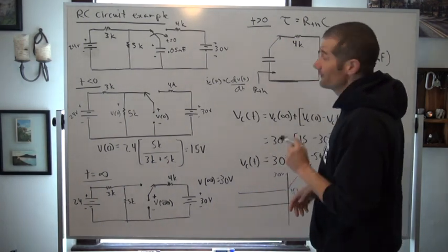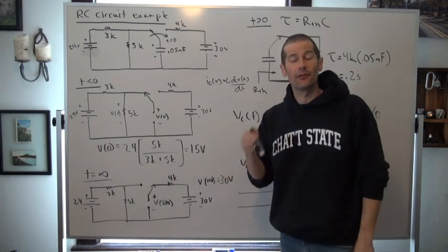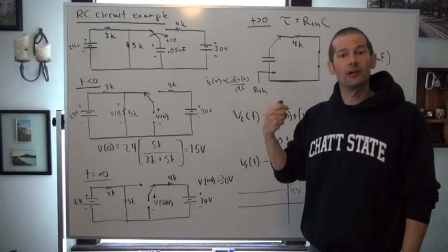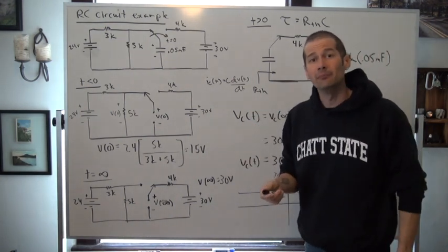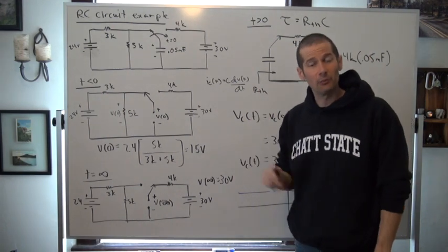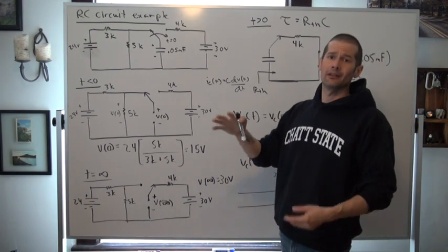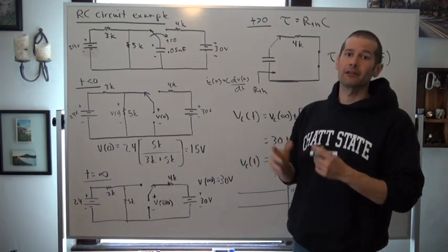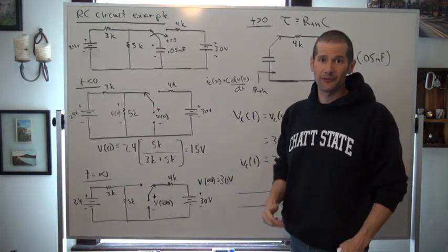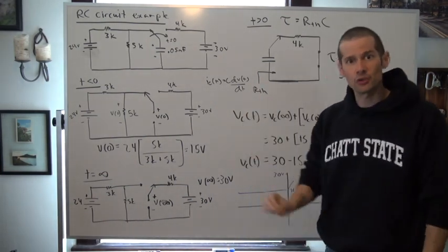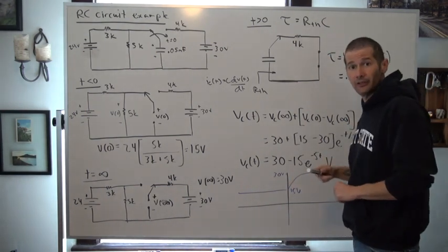Now, we derived this the other day, in which tau was equal to R Thevenin times C. If you watch the Thevenin equivalent circuit video, I say R Thevenin because it's the same process that we do in order to find the Thevenin resistance within a circuit. We turn off all sources and then we equate that resistance to that capacitor, because it's the resistance that the capacitor sees that really drives the exponential portion. So if we take a look here, tau is equal to R Thevenin times C.